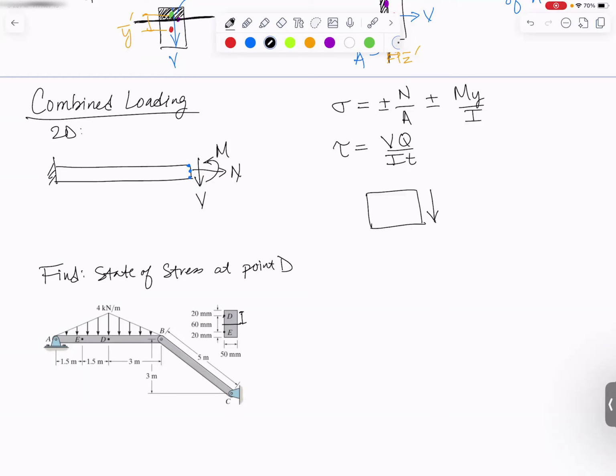So our shear stress, we said, was going to go down on this right edge. So it's got to go down on the right edge. That wouldn't be an equilibrium. So we have to draw a countering upward one. That's still not an equilibrium. That would start rotating. So we have to draw another pair on the top and bottom edges just for equilibrium purposes. So when you're done, you should have these guys head to head and tail to tail all the way around.